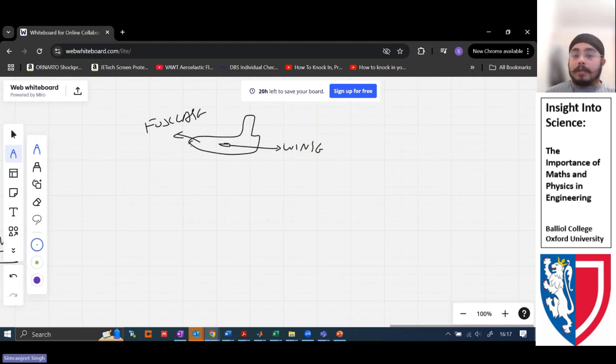When we do practical examples, when the airplane, for example, is ready to fly or to begin operation, the manufacturing industry says we are ready to sell this airplane. How do they test this? They test each and every component of this airplane. It has a rotor, wings, fuselage, aileron, and multiple other components as well. They test those components separately under the wind tunnel. The wind tunnel tells them how much drag they might come across, and how much thrust it can actually generate.